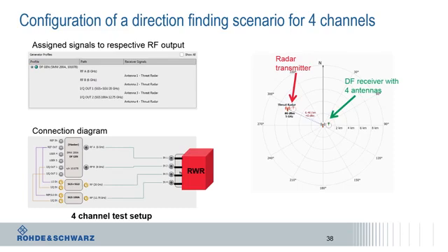The master is the SMW200A, which provides the 2 RF sources. SGS plus SGU can provide additional RF sources for multi-channel setups. They are fed with the IQ signals which are generated inside the SMW200A. So now you have 4 RF channels, and these channels can then be directly connected to the radar warning receiver, which in this case has 4 channels.